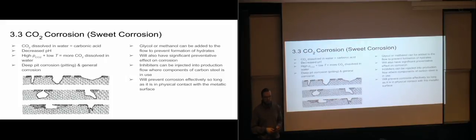So that means that if you have a well flow where you're not utilizing the entire cross-section of the pipeline, so you're not filling it up from bottom to top, you're basically just filling up parts of it, and it's just running along those lower parts. Your inhibitor will only be in contact with the lower parts of the pipeline.